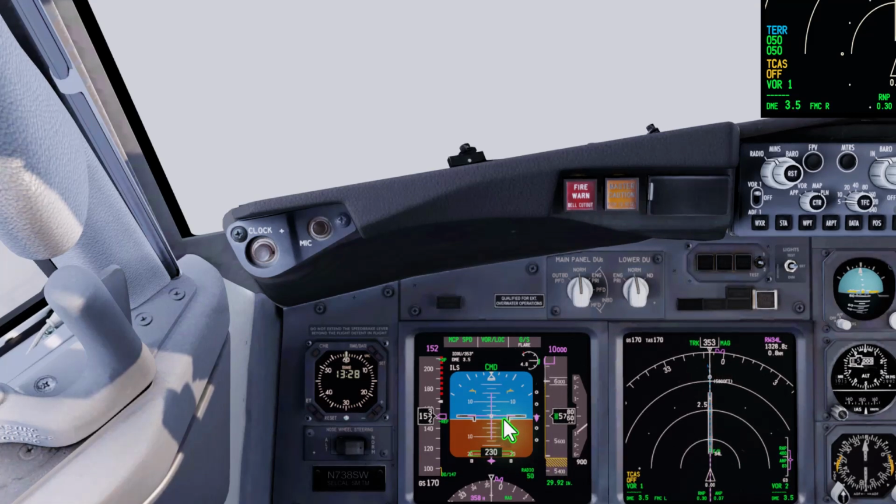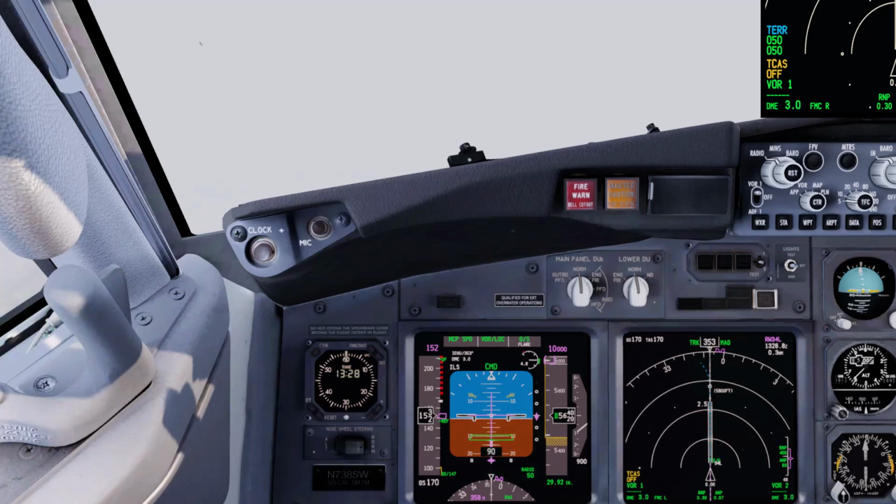But this is where we're starting to fish and cut bait. At 200 feet, now notice that the runway symbol is moving up. At 100 feet, we just saw a flash of the surface here. Here's where we're looking. Out here as a pilot monitoring, the pilot flying is in all likelihood going to be very much involved in watching this flare arm.